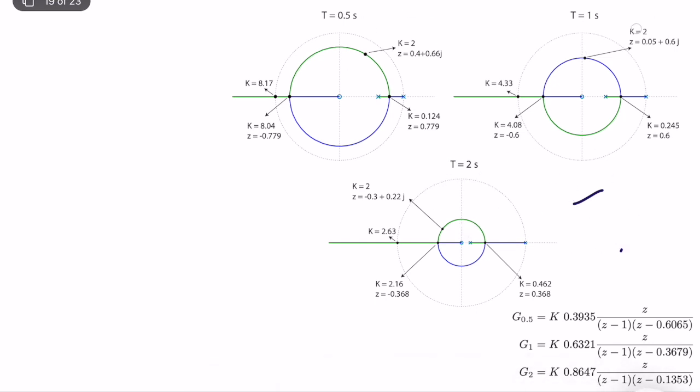One thing you should look at first is the range of K values that makes the system stable. Obviously, when K is equal to 0, all systems are marginally stable, not asymptotically stable, because we have a pole at z equal to 1. When we increase K, they all become stable because the 2 poles here approach each other.